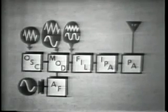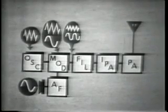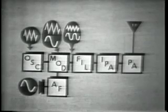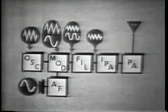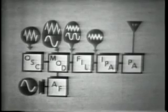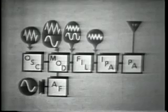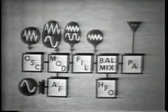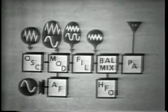We then insert a filter which will pass only one of the sidebands, and of course we can select either one, and we'll reject the other one. Thus we have only one sideband to be transmitted with all of the transmitter's power. At this point, if we desire to operate at a frequency other than the frequency of the sideband, we can change the sideband frequency by mixing it with another RF signal in a balanced mixer and selecting the sum frequency.